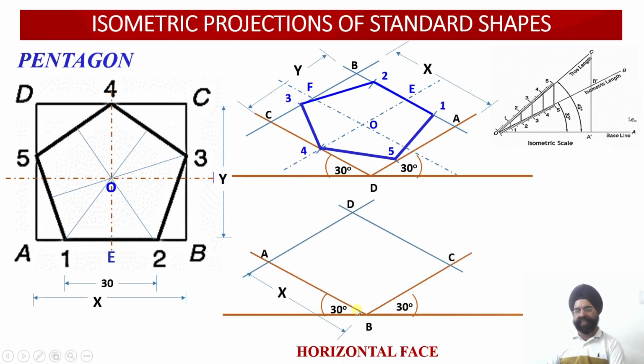This is my x-axis, this is my z-axis. Now earlier I had located AB over here. Now if I locate my AB over here, once again A to 1, B to 2 distance I will be marking, and then this is my axis point. So measure A to E and measure B to F or A to F. So this axis point will be located.